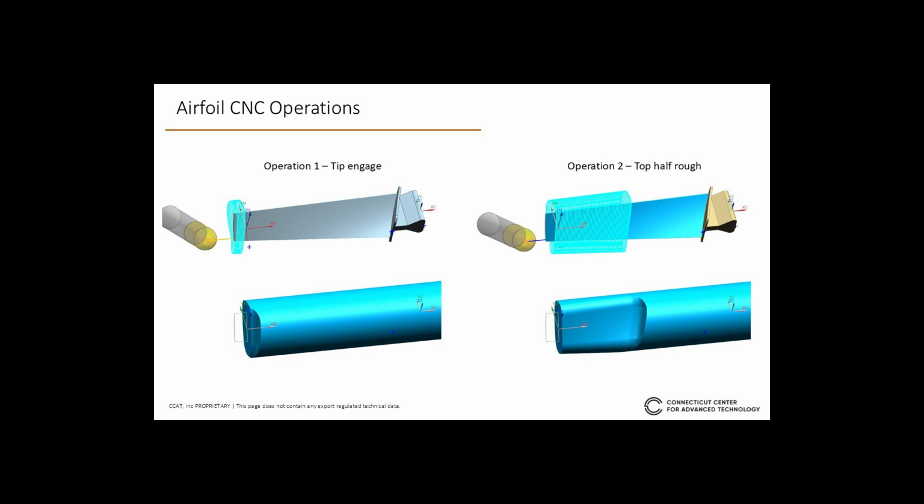In our case, we left the tip free, but in leaving the tip free, we tried to employ machining strategies that would minimize tip deflection. So even though we were trying to induce, or be able to measure, tip deflection or part deflection, we still employed a machining strategy that would minimize it.